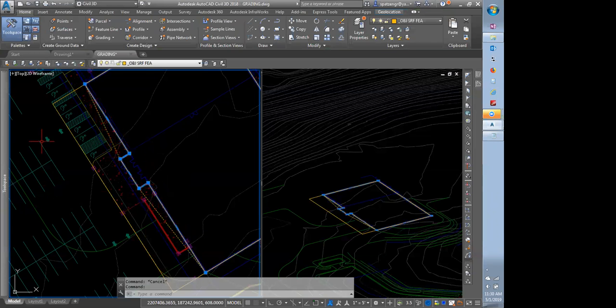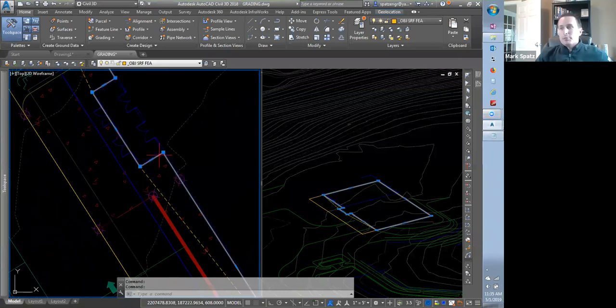Hold on a minute. Okay, so this is a real scenario here. We have this first floor, and then this is the question. What do we want to do here? This vestibule, do we want the vestibule to maintain at first floor elevation or be at the same slope as the sidewalk? Because that sidewalk's coming down 2%. Right now, this vestibule's at 0%, right? And then from here to here, it's actually a little steeper than 2%.